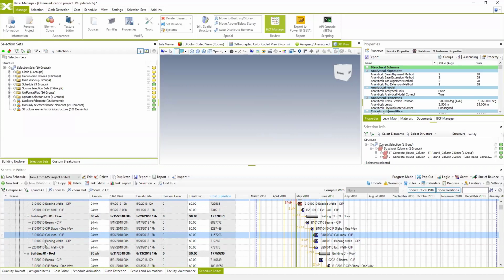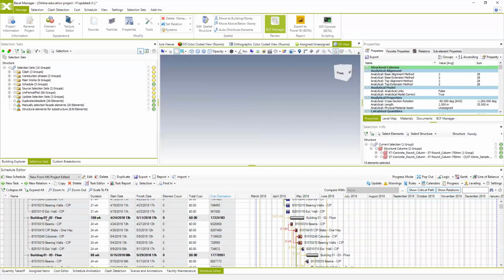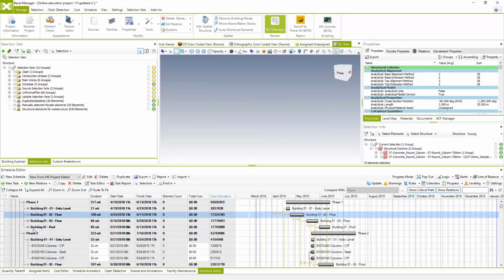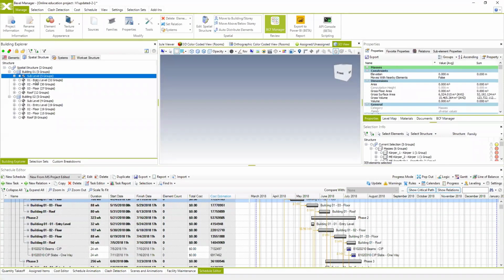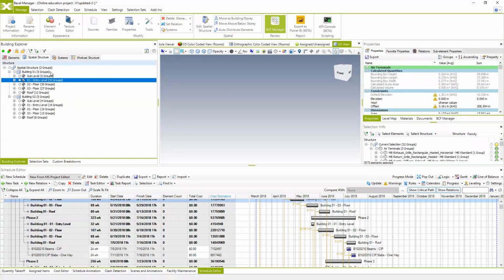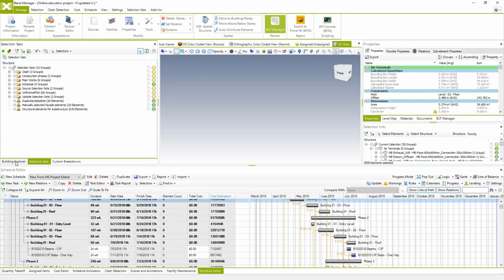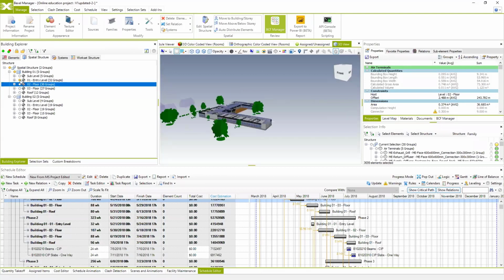And this system actually works from the top to the lowest level of your hierarchy. So you can automatically link your high level groups of BIM model elements, and the system will segregate them and automatically filter these to each leaf task. Usually, for example, these imported schedules are segregated into different hierarchy levels. In this case, of course, based on the building stories, and BEXEL Manager has automatically segregated elements based on the stories. We presented that in the previous sessions.